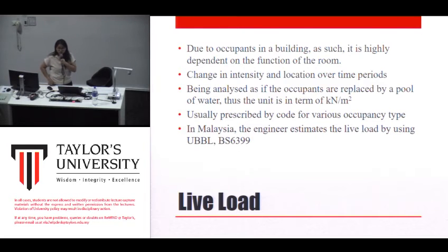Live load, imposed load, movable load. All right. So when we identify the live load of a building, or rather of a space, it depends on the function. Live load never depends on how much furniture you put in, or how big it is. No, it depends on the function of that space. If this room is a bedroom, the live load will be slightly lower compared to probably a lecture theatre, because of the density of humans inside